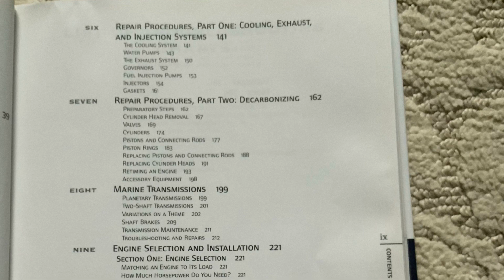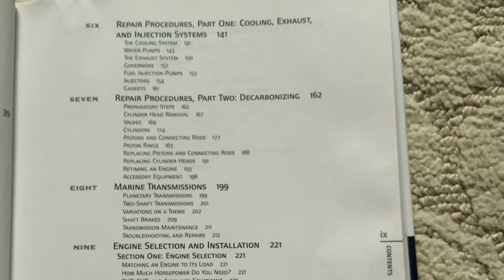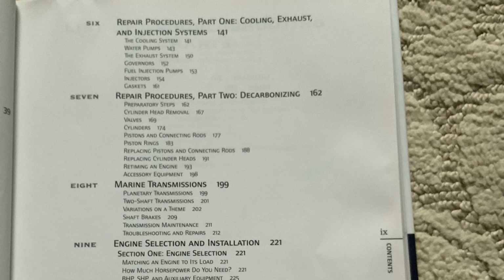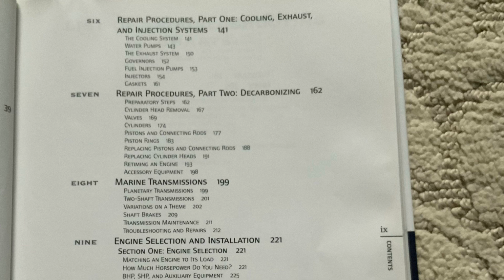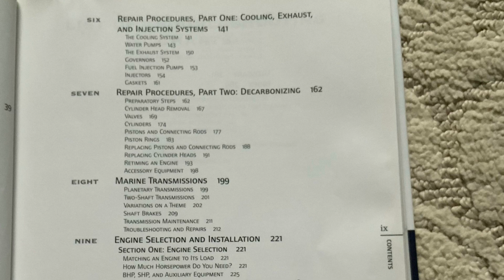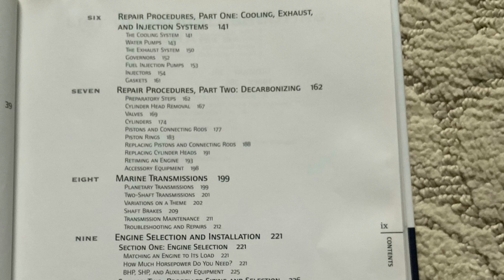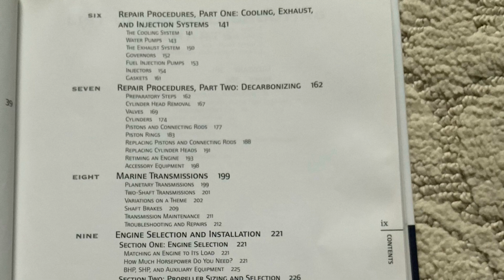The increased pressure is used to drive the piston back down the cylinder, resulting in what is termed the piston's power stroke. The engine has converted the heat produced by the burning fuel into usable mechanical power. For this reason, internal combustion power plants are sometimes known as heat engines.